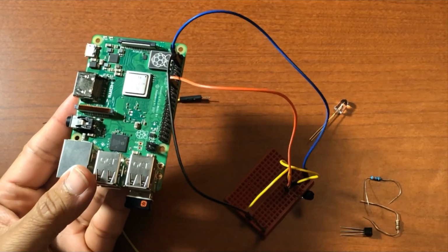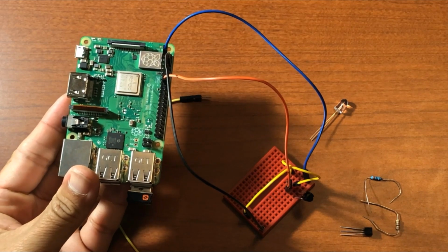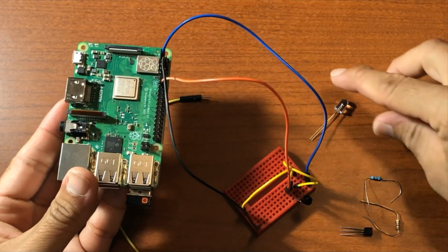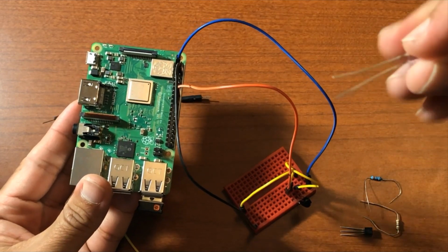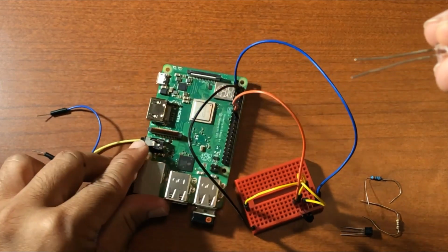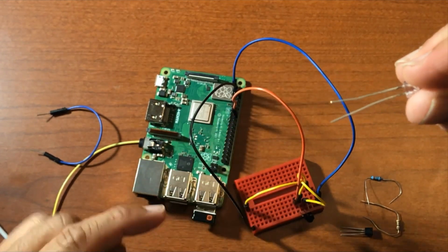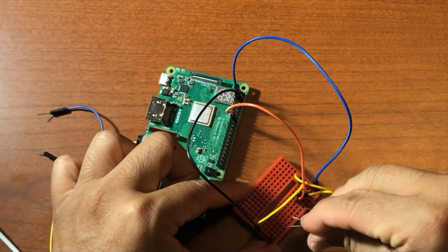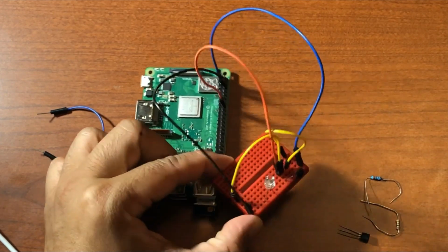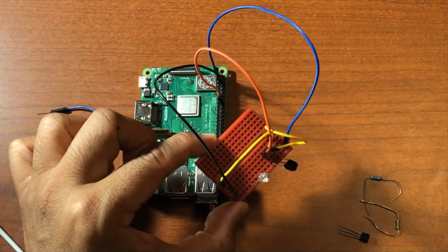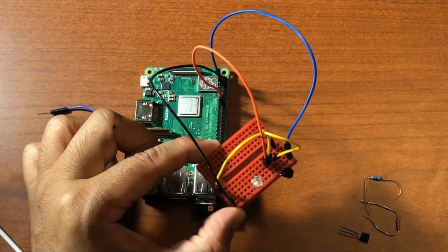So that's the wiring for the infrared receiver, and now we're going to wire up our IR LED. So here's the IR LED. We're going to put it on the circuit. Make note of the cathode and the anode. Of course, in this case, the longer pin here is our anode and the shorter pin here is the cathode. So I'm just going to insert that into the circuit. What we want to make sure is that these are facing outward in the circuit. That way we can orient our circuit and point it to our TV when we are trying to emit the infrared signals.